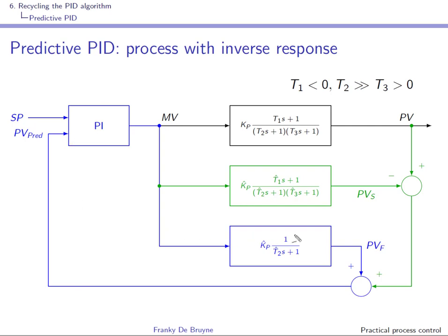system, right? But we have to make sure that we detect disturbances at the output, and that we see that there are essentially static gain mismatches. And this you can do by comparing the overall model with the actual PV, and this comparison yields an error that you add.